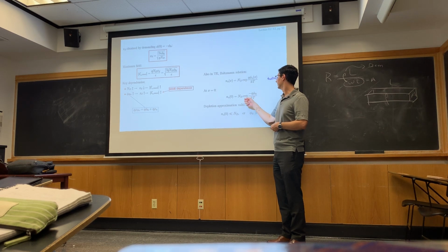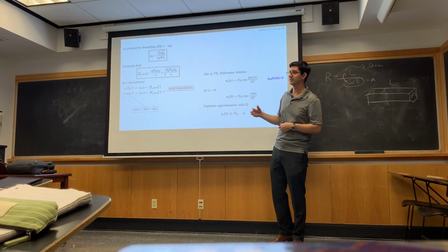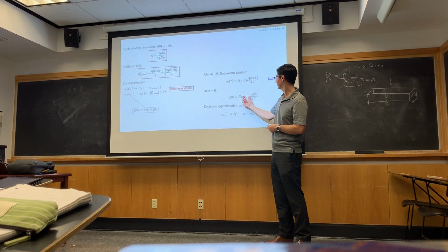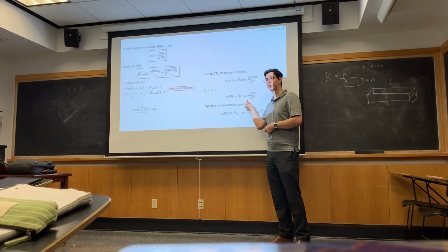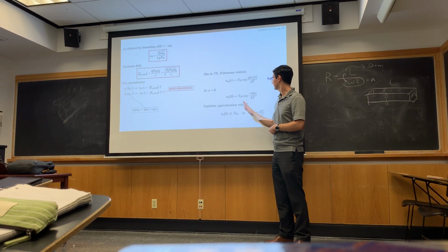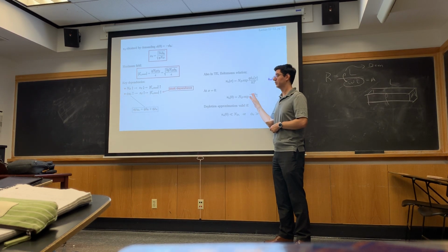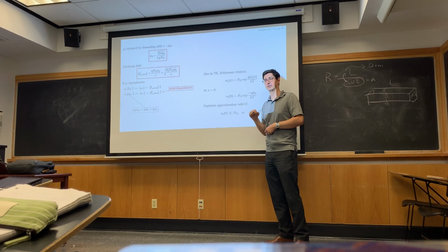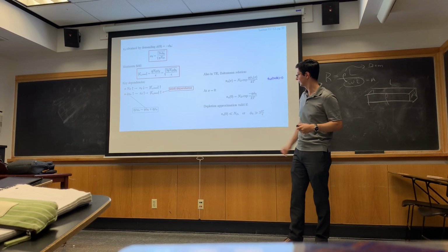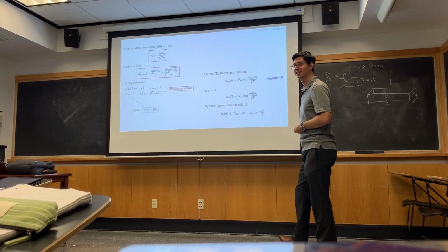Exponential of 60 millivolts divided by 25 millivolts thermal voltage is equal to 10. Exponential of minus 60 millivolts over 25 millivolts is equal to 1/10. Yes, one person understands. It made a difference. But that's where it's coming from.